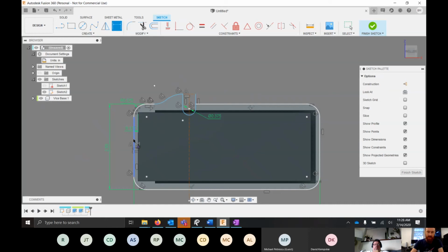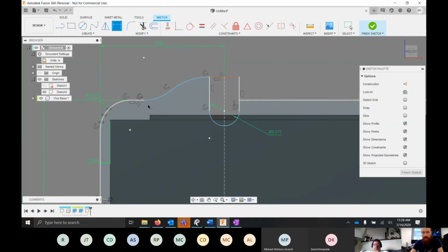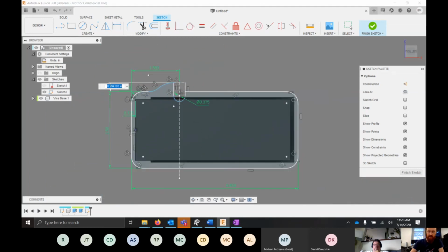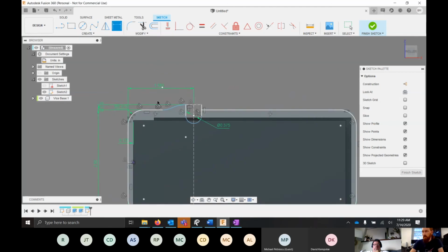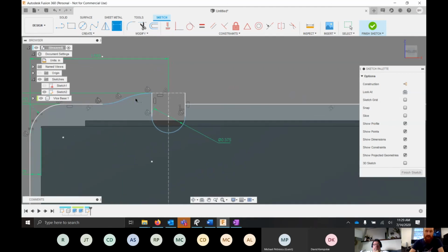We'll do our sketch dimension, and we'll specify this line, which is 1 9/16. And then it's kind of weird how it calls it out in the drawing, but it's saying from this line to this line, so along this area, is 1/8 inch. And then I have to specify the radii of these two arcs.